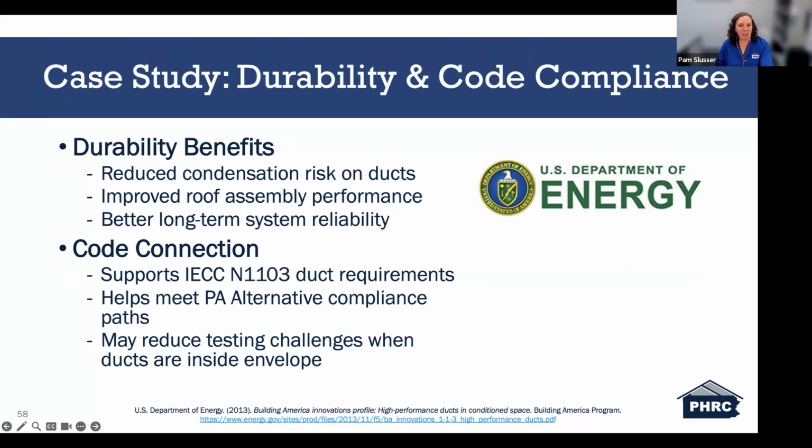From a durability standpoint, keeping ducts inside the conditioned space reduces the risk of condensation forming on duct surfaces. It can also help prevent moisture-related issues over time. It also contributes to better overall roof and building assembly performance, particularly when the ducts are no longer exposed to those extreme attic conditions. In terms of reliability, the system tends to perform more consistently and it experiences less strain.